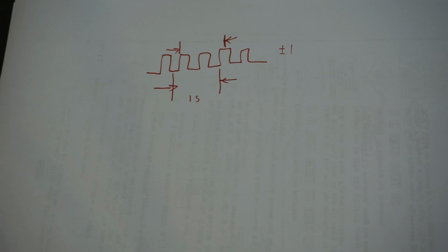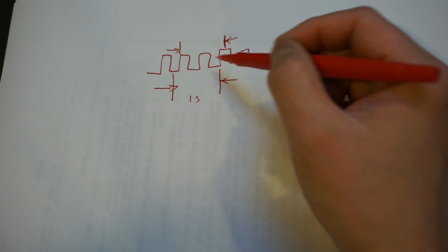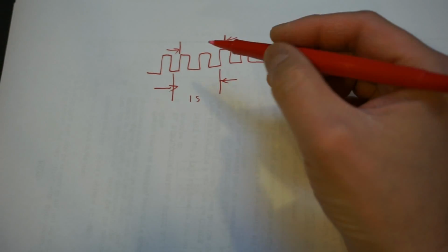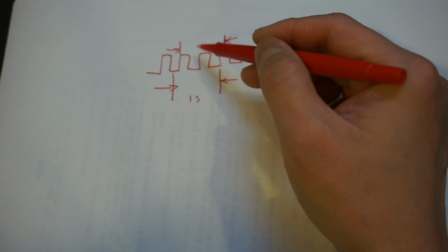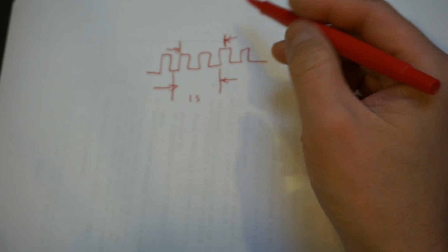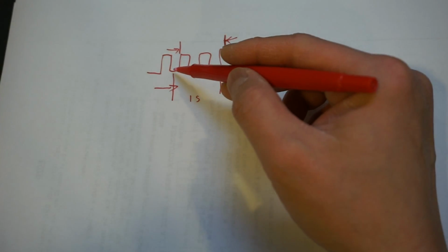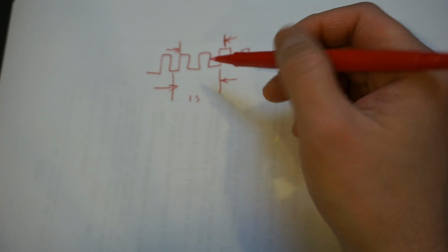So how do we make the measurement of a lower frequency, or a frequency comparable to your gate opening duration, more accurate? Well, one obvious choice is, let's say we are measuring a 5 Hertz signal, I can make the gate very long. I can open the gate for, let's say, a minute, right?